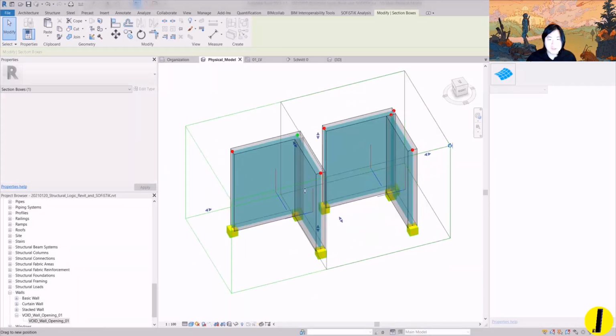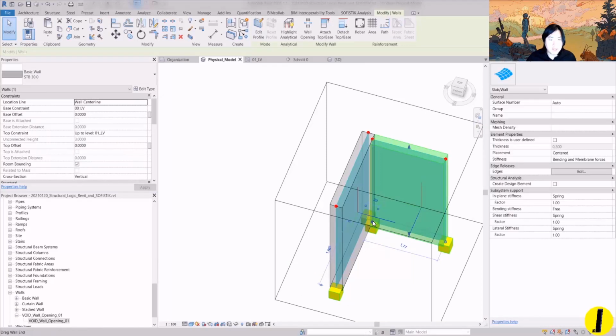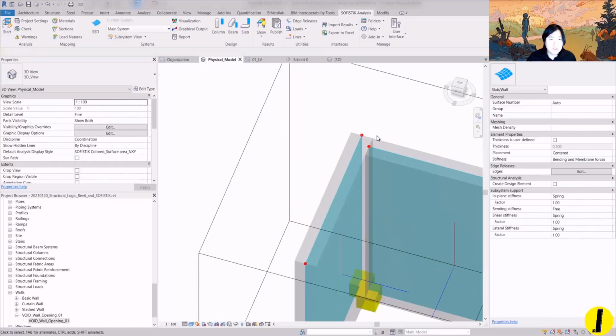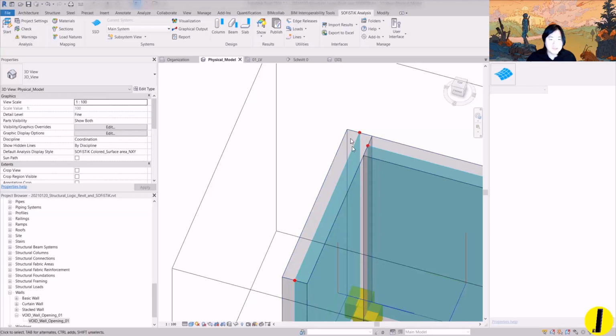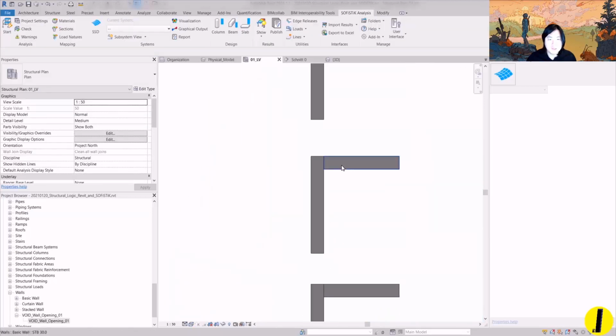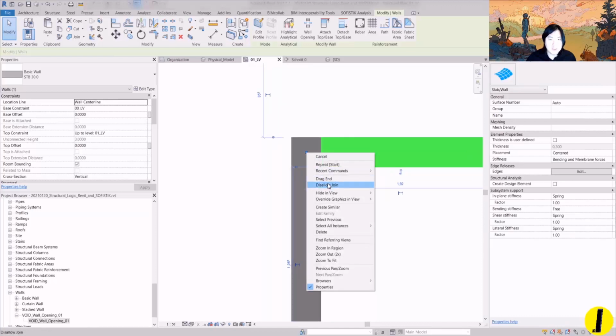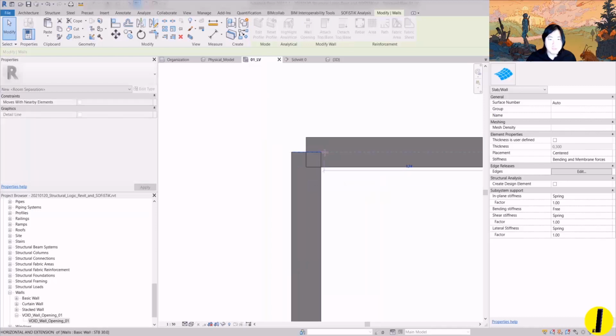Here we have another example. You might model your Revit wall using, you see here we may have this butt joint, but perhaps let me go back to plan. Here in this case, you see a small symbol, which means we disallowed wall join. So sometimes we can make it join, then they are joining, or you can select this node point, hit the right mouse button, and when you disallow join, you can push it back.